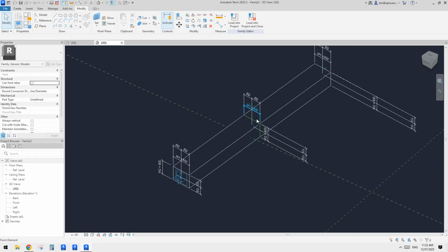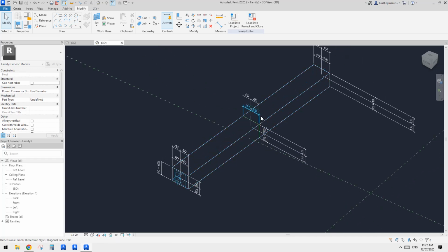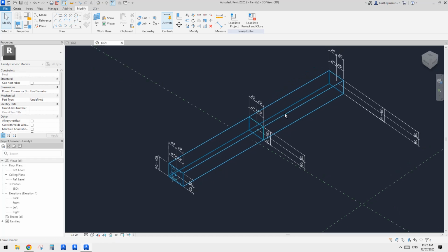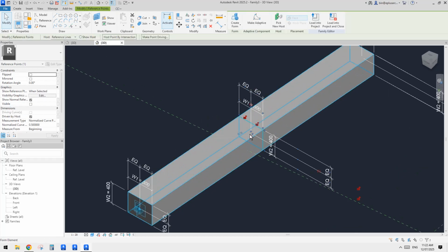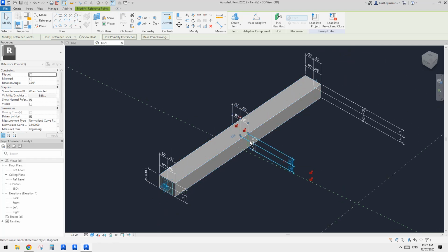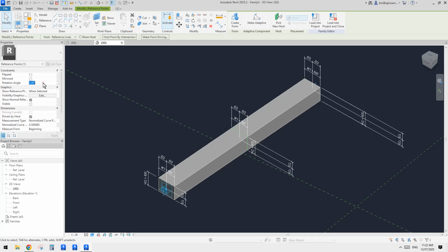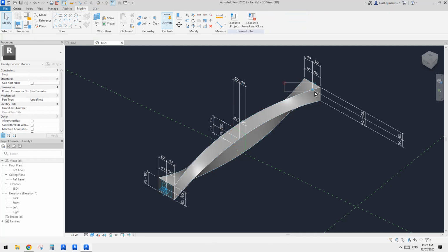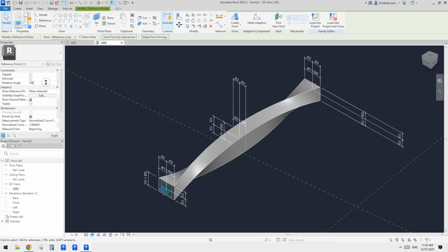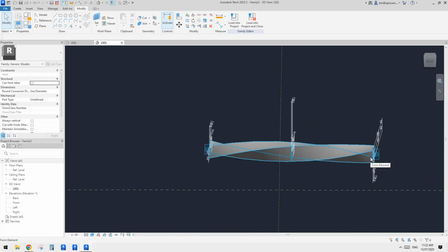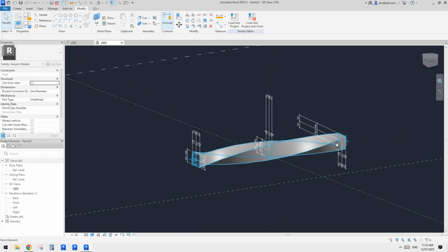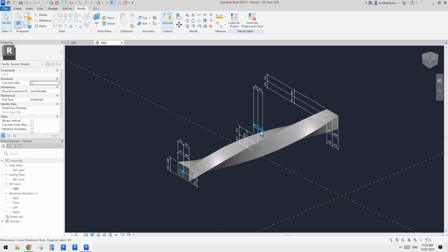Sometimes you need to do it first and then rotate it. If you rotate first and then create, you get some weird shape. Okay, so type SD to change it to solid, and then let's just try. I want the whole thing to rotate like 180 degrees. So I'll rotate this one by 90 degrees, and then this point about 180 degrees. So it works, from here to here, right? So rotate 180 degrees.